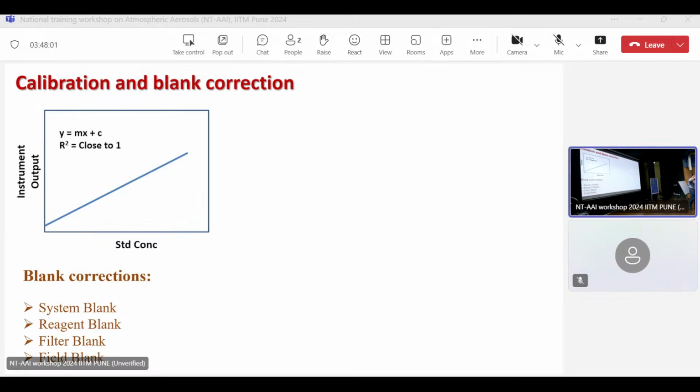I was telling you that we add some 20 micrograms on a filter and run it as a sample, because the system has internal calibration. In every run you put some 5 ppm methane, and that signal you use as a reference to get the concentration in your sample. But for the majority of instruments, it is this way. Validation is a different thing. Whatever data you have produced, how can you make sure it is correct? Put anything in the instrument and something will come out. How to validate whether that is correct or not? We will talk about that.